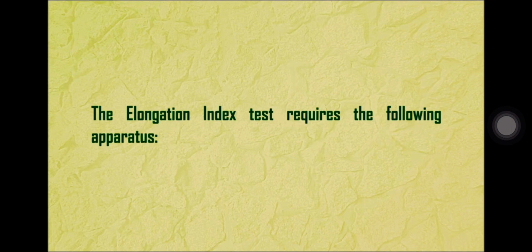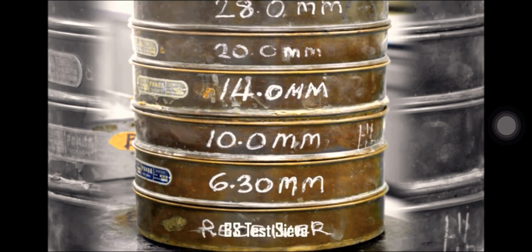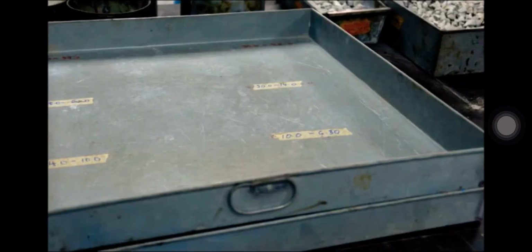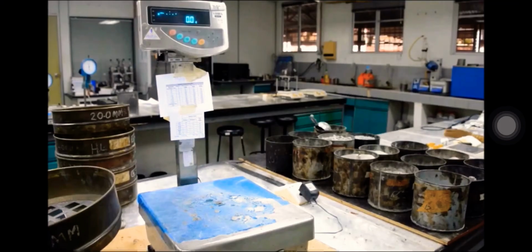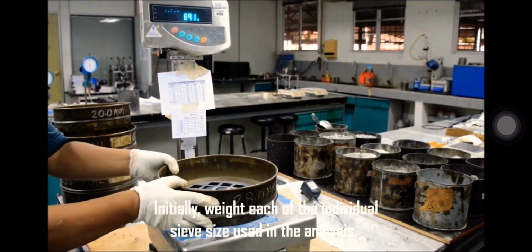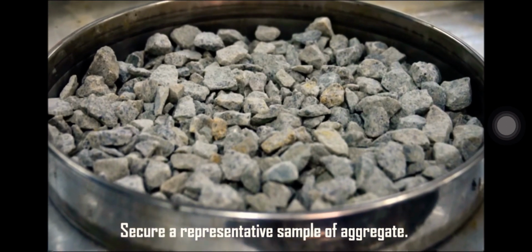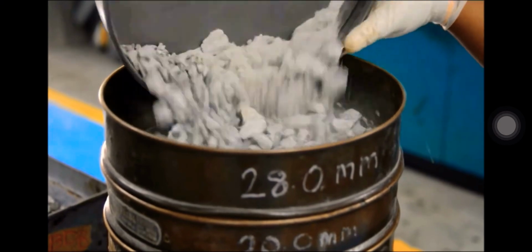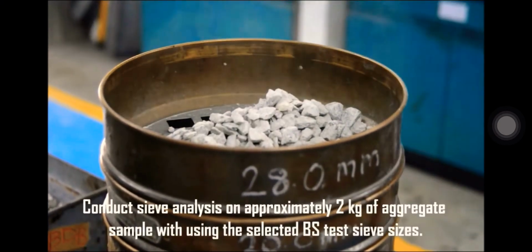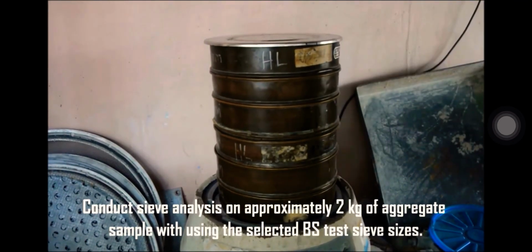The apparatus is the length gauge, BS test sieve, mechanical sieve shaker, tray, and balance. The procedure is: initially weigh each of the individual sieve sizes used in the analysis. Secure a representative sample of aggregate. Conduct sieve analysis on approximately 2 kg of aggregate sample using the selected BS test sieve sizes.